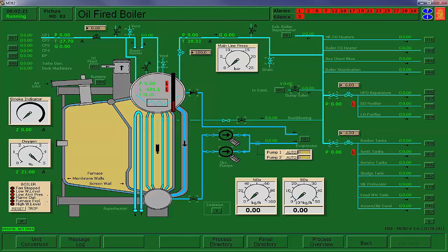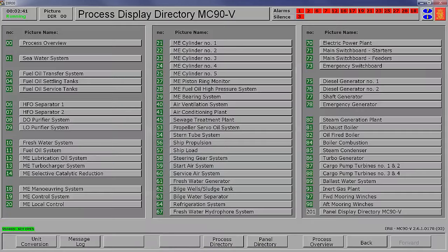So we want our desuperheated steam stop wide open. We need to open for the circ pumps. Their suction from the mud drum return back to the steam drum. All right, we've got that. Now we got to put some boiler water in there,